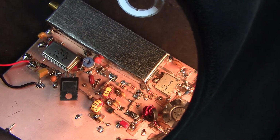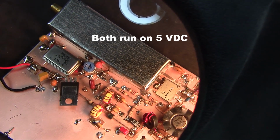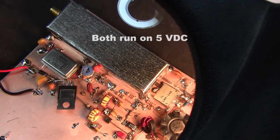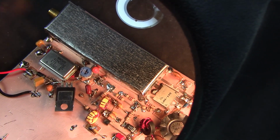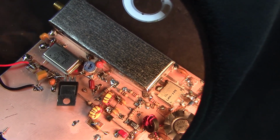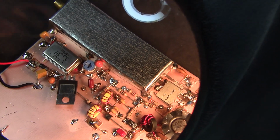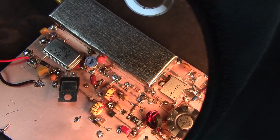And I'm coming off the 40 megahertz TCXO module. Of course, we could use my one transistor harmonic oscillator as well, but this was a quick and dirty way of getting a sine wave into the Schmitt trigger. So this is a much simpler circuit. We're just using one inverter.